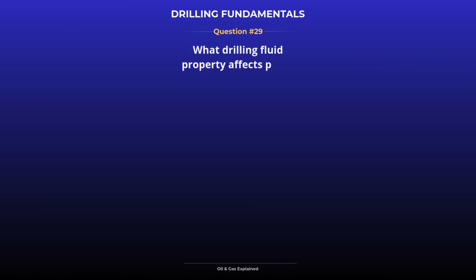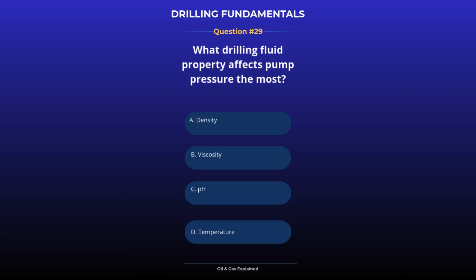What drilling fluid property affects pump pressure the most? Higher viscosity increases frictional losses, resulting in higher pump pressure.